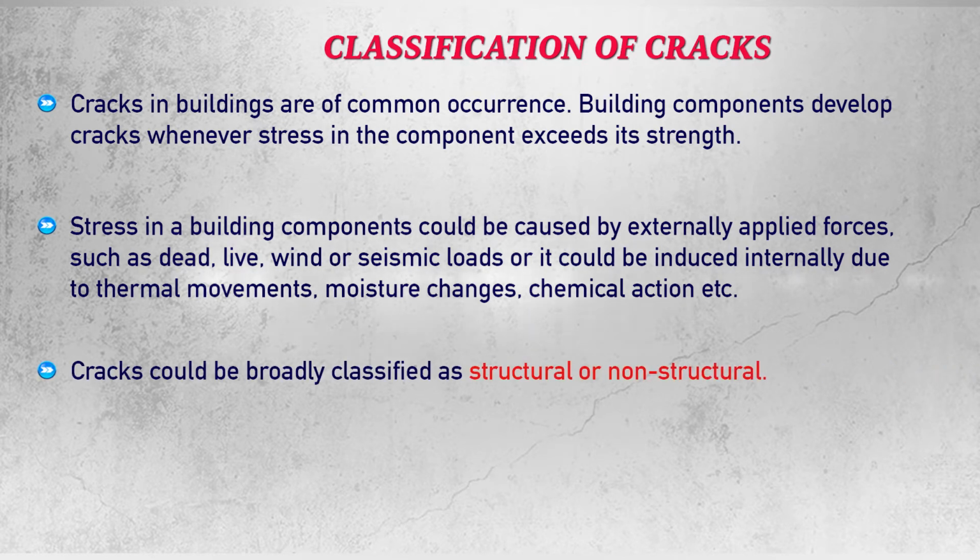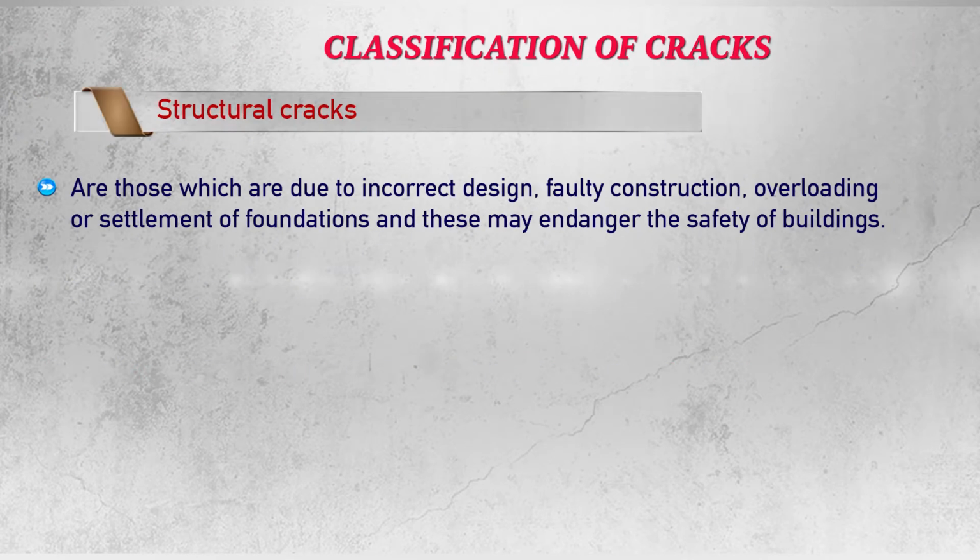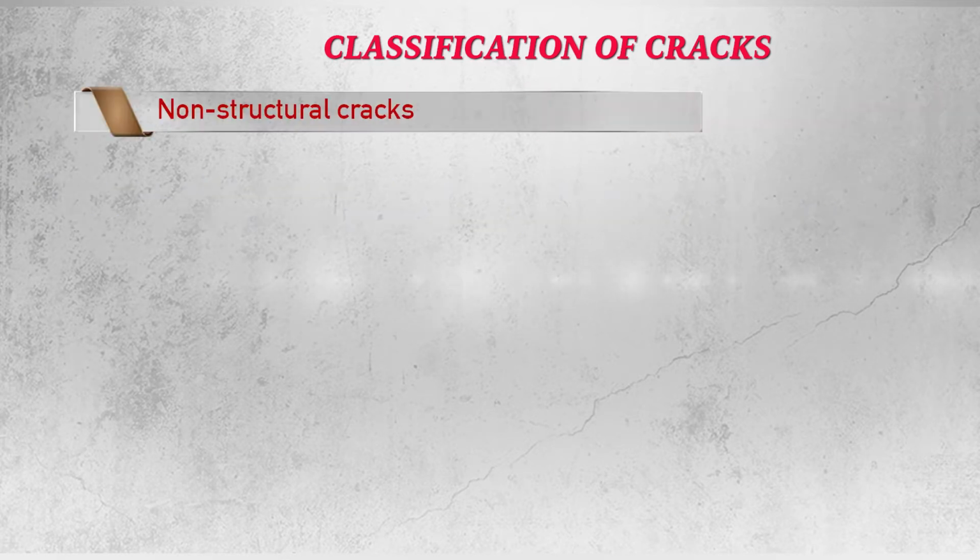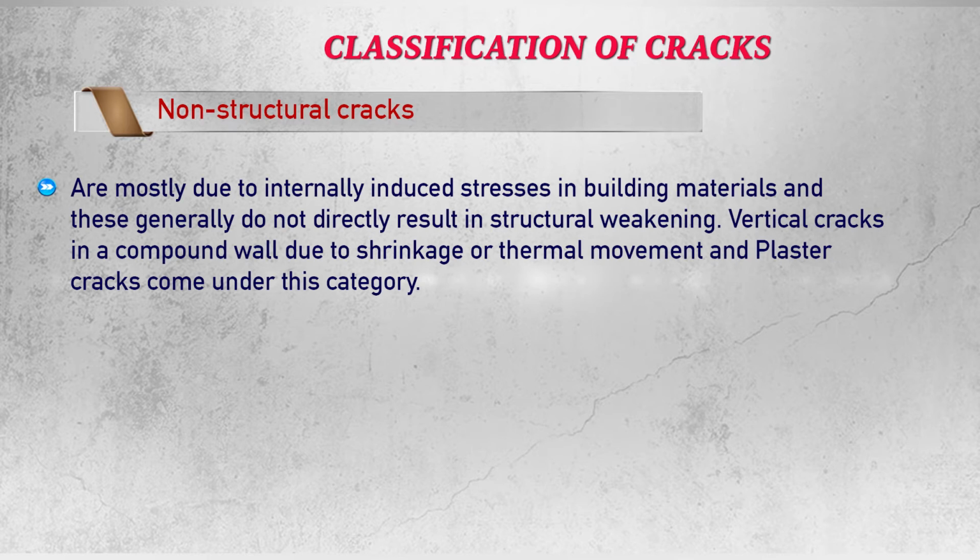Cracks could be broadly classified as structural cracks and non-structural cracks. Structural cracks are those which are due to incorrect design, faulty construction, overloading or settlement of foundations, and these may endanger the safety of buildings. Non-structural cracks are mostly due to internally induced stresses in building materials, and these generally do not directly result in structural weakening.